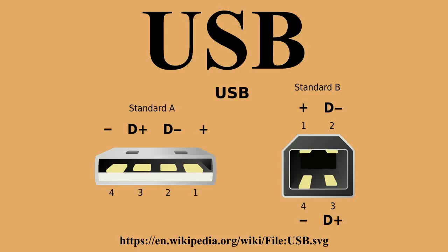Therefore, in general, each different format requires 4 different connectors, a plug and receptacle for each of the A and B ends. USB cables have the plugs, and the corresponding receptacles are on the computers or electronic devices. In common practice, the A end is usually the standard format, and the B side varies over standard, mini, and micro. The mini and micro formats also provide for USB On-The-Go with a hermaphroditic AB receptacle, which accepts either an A or AB plug.